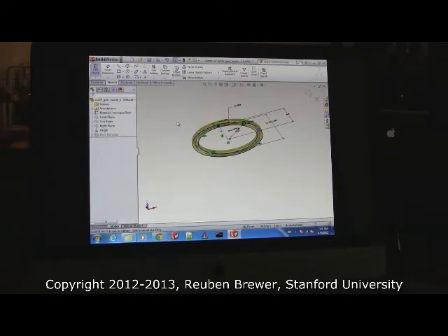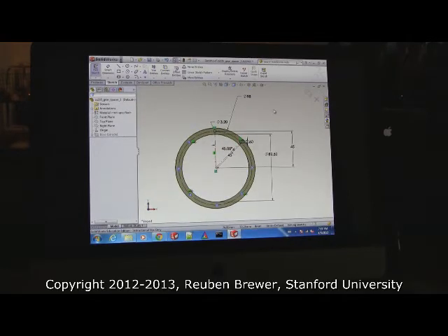So the way that you get to standard orthographic or isometric views: orthographic is always straight on along one of the primary axes. Isometric is at some weird angles. See this button right here? View Orientation. These are the different views. These boxes that only highlight one side give orthographic views. These diagonal ones give the diagonal views. This is the most important one right here, Normal To. And now my sketch comes back up normally. This will happen constantly. Get to know that menu.